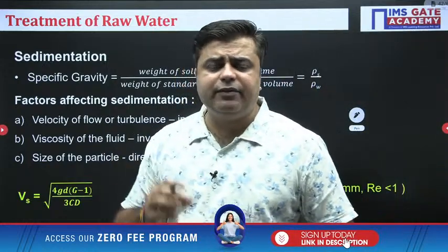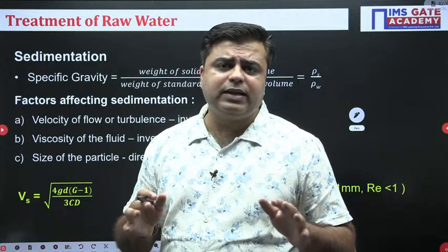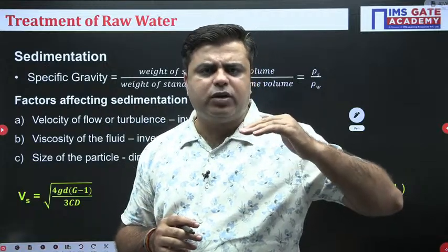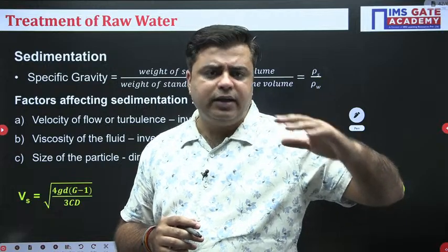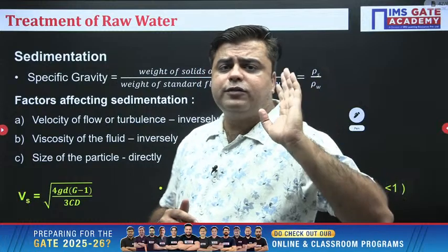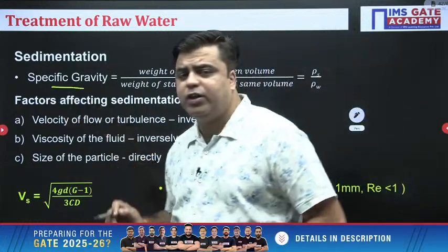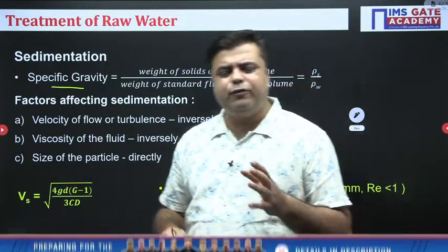Sedimentation is a technique in which we allow the solids to settle under their own weight. No chemicals are added. We simply make the water flow so smoothly in the tank that the solids will settle under their own weight. The phenomenon of sedimentation is governed by a single factor which is termed specific gravity.